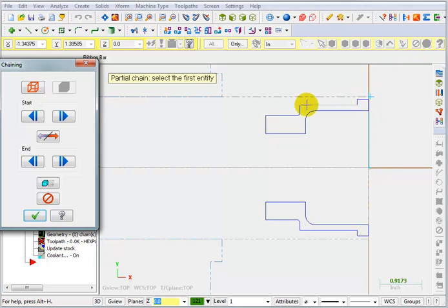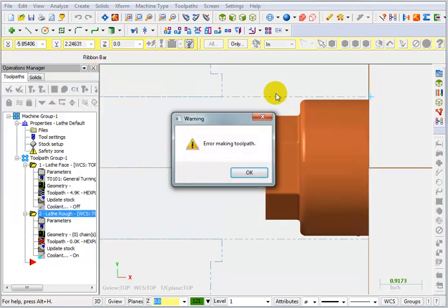And you can see there's a notch here. Well, that notch is the slot. So if I was to use this as my turn profile, I would be turning this diameter down way too small. And also, with that hex on the front, it depends whether I'm getting the high point of the hex or whether I'm getting one of the low points on the flat side. Could make a big difference in what I actually get for turning down this profile. Let me close that.